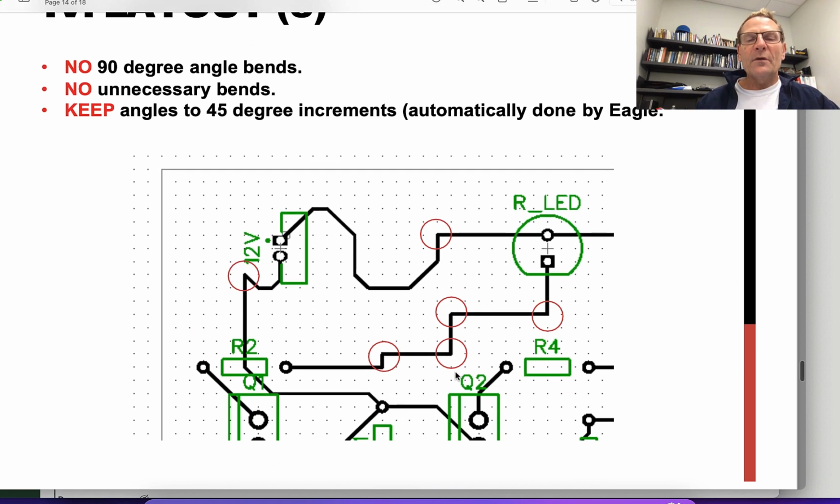In our layout, because the layout now represents the actual electrical connections that will carry signal and power between components while this device is in operation, we want to realize that electrical energy moves through traces in either efficient or not very efficient manners, and our goal will be to create this pathway in an efficient manner. So we won't want to have a lot of sharp turns or jogs up and down and around, but rather we would like rather straight connections between components as are shown here. We don't want to have any 90-degree bends.